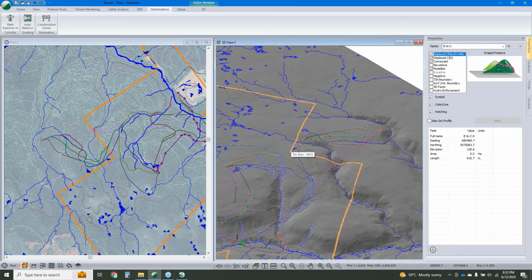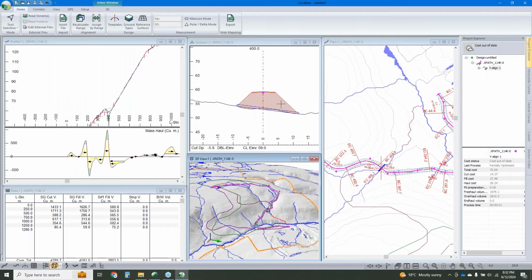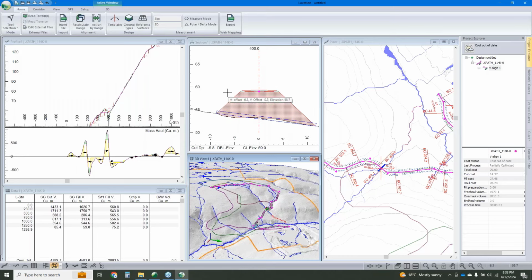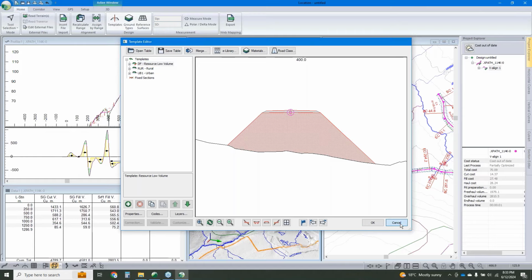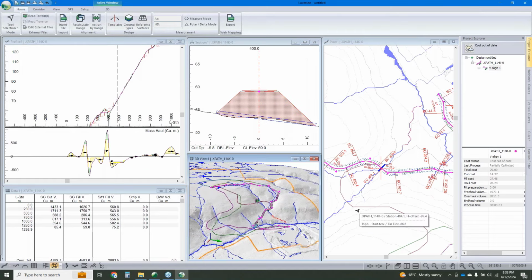And with that, it's not something that you have to set up every time. So for example, my cross-section geometry, just this gravel road, I was comfortable to just run with that, because I've got it set up to meet my default. So we can customize our cross sections, our curve specs, etc., and save those out, save them as our normal.tpl in the cross section case, and then when you open the software, that's what's there. So set it up, don't worry about it unless you want to deviate from it, and away you go.